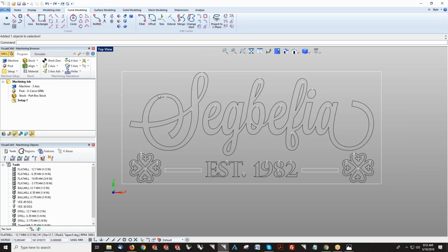So the first step is you want to clear the material out between these areas in here, right? You want to hog all the material out that is in here. Am I correct? Exactly. Okay. Now, would you like the cutter to go past this edge, or do you want the cutter to completely stay inside this rectangular boundary? It needs to stay inside of that boundary.